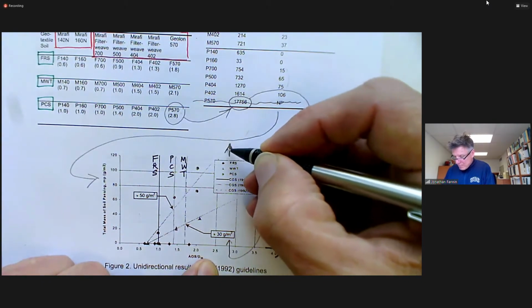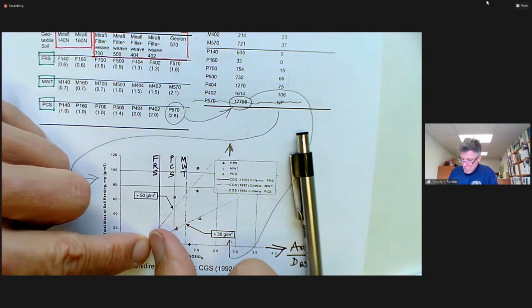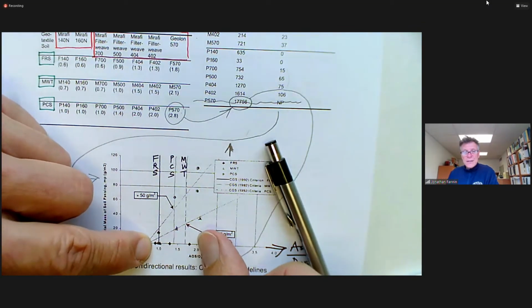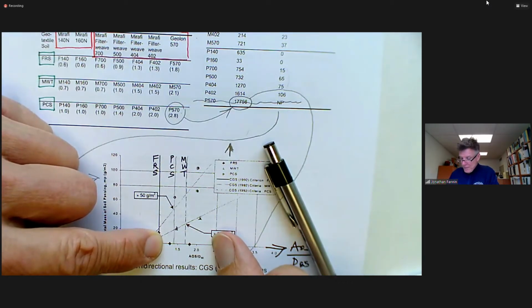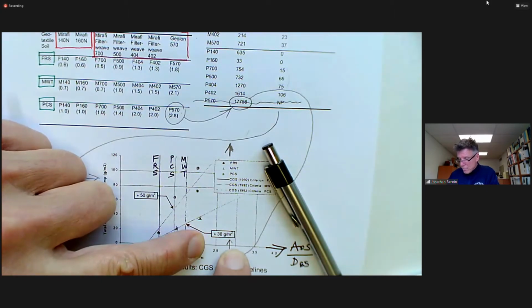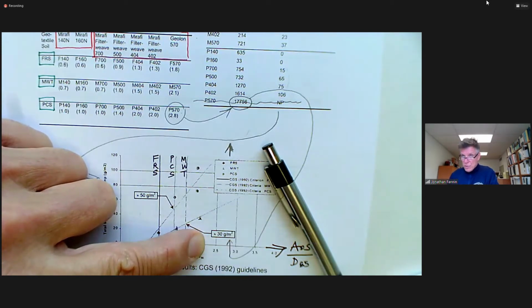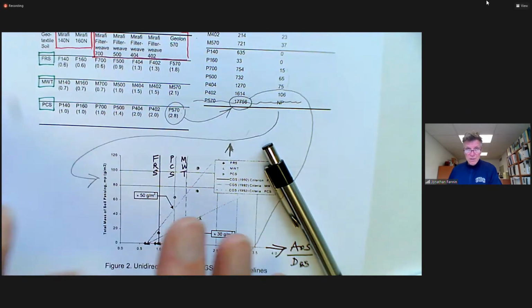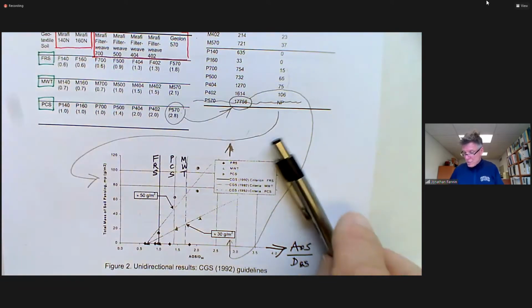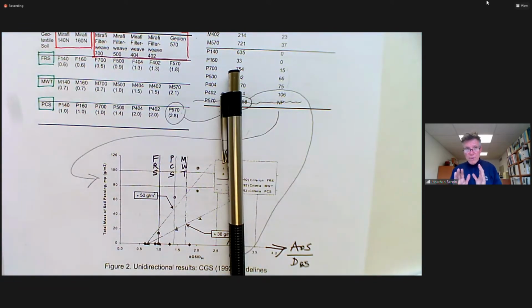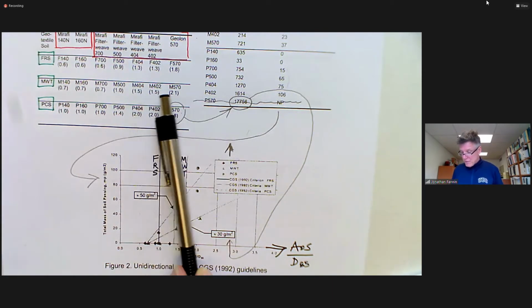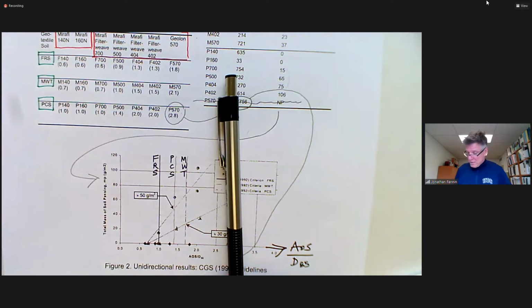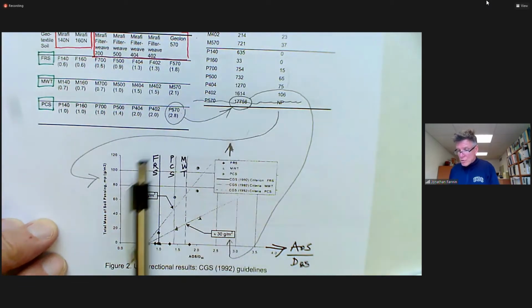So we see a couple of truisms here. Number one, how much conservatism is there in design practice? And you can exceed it relatively comfortably, but there will be a threshold where, especially for a woven geotextile, when you hit material piping through it, your geotextile is so open as a woven material that the soil will just continue to pass through. So we recognize a sensitivity. The design practice is conservative, the empiricism is conservative, but there's an enormous sensitivity to it opening up too much.